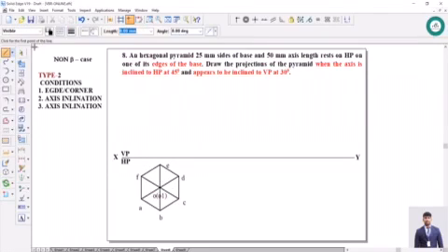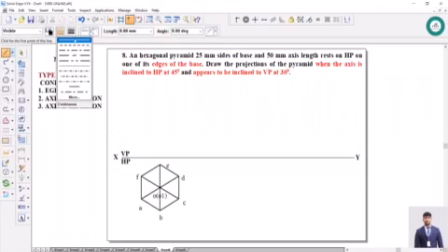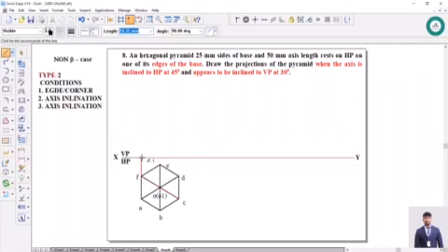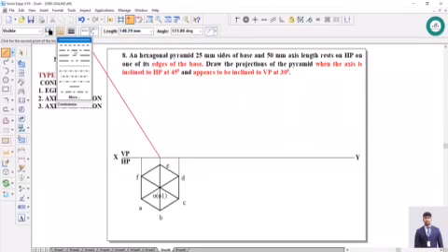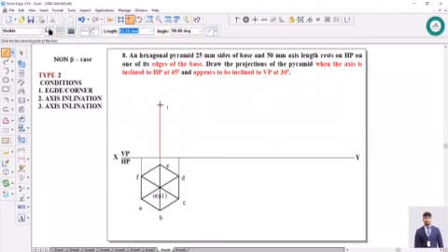To get a front view, project the line to the XY line from all these points. So after projecting this, raise the height of an axis from the center only. Select the axis line. What is the height of this? Given as 50 mm. Once that is done, take the suitable type and width. So join this point and this point. From the front view, OB edge covers the axis, so I will be covering this particular axis.